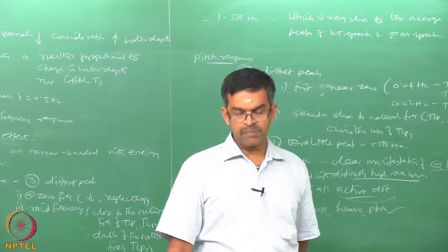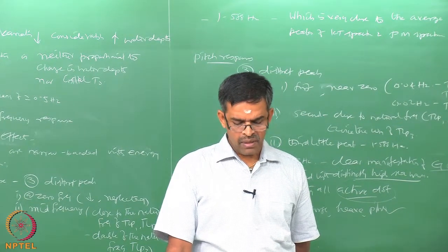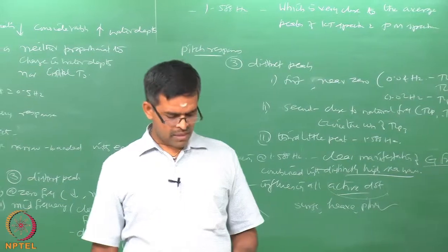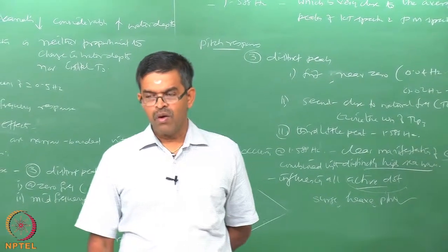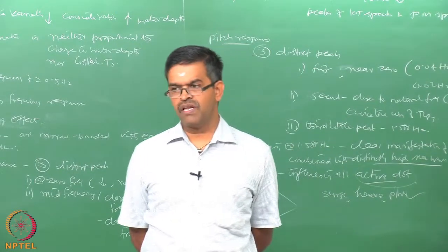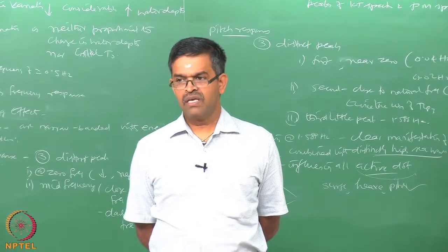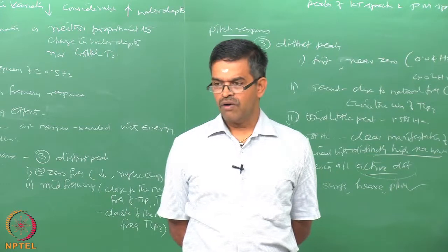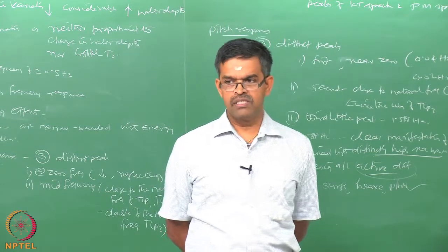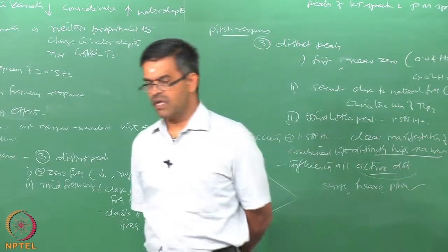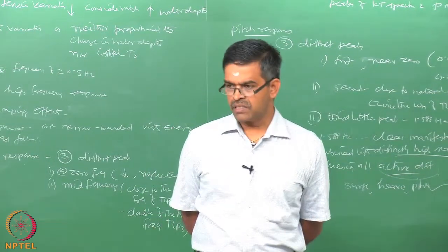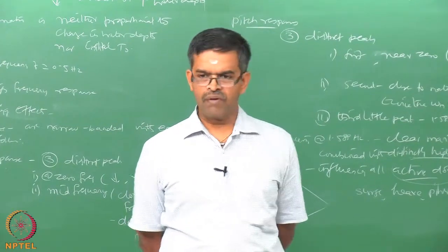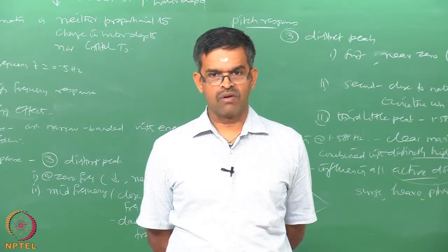Clearly, the peak seen in the response in all 3 active degrees of freedom, namely heave, pitch and surge, occurring at the average sum frequencies of PM spectrum and KT spectrum is a clear manifestation of this combination. While TLPs are expected to be rigid in stiff degree of freedom, in this specific case one can see that heave is activated even at 1.58 hertz frequency, which is very dangerous for a given system, because heave is supposed to be the stiff degree of freedom. So, displacement in heave degree caused by the seismic excitation in combination with distinctly high sea waves is actually an interesting challenge study, which tells me whether the platform geometry is stable and safe under this given combination.